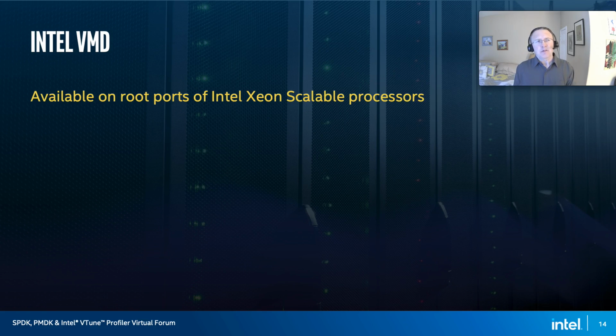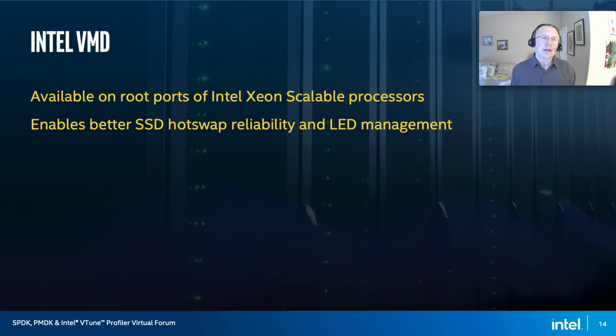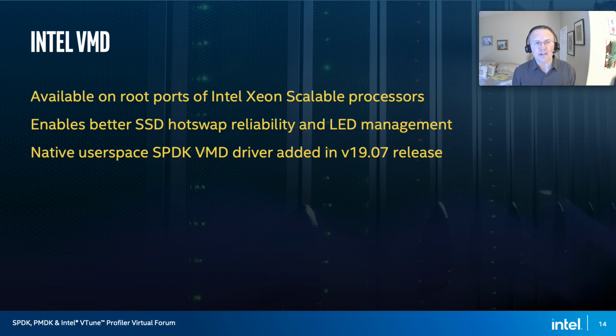Then Intel VMD. VMD stands for Volume Management Device. This is available on root ports of Intel Xeon Scalable processors. The feature itself enables better SSD hot swap reliability and also LED management. What it does is it allows a host driver to, in all cases, be able to intercept any sort of hot plug events. So on systems where maybe the system firmware, BIOS, doesn't have all the hot swap reliability that you depend on, you can have a driver that can help manage that instead.